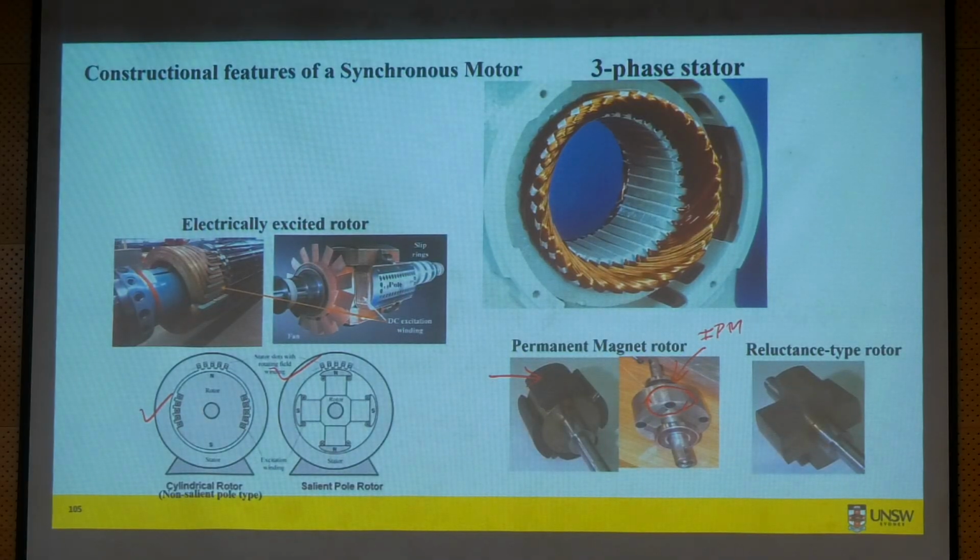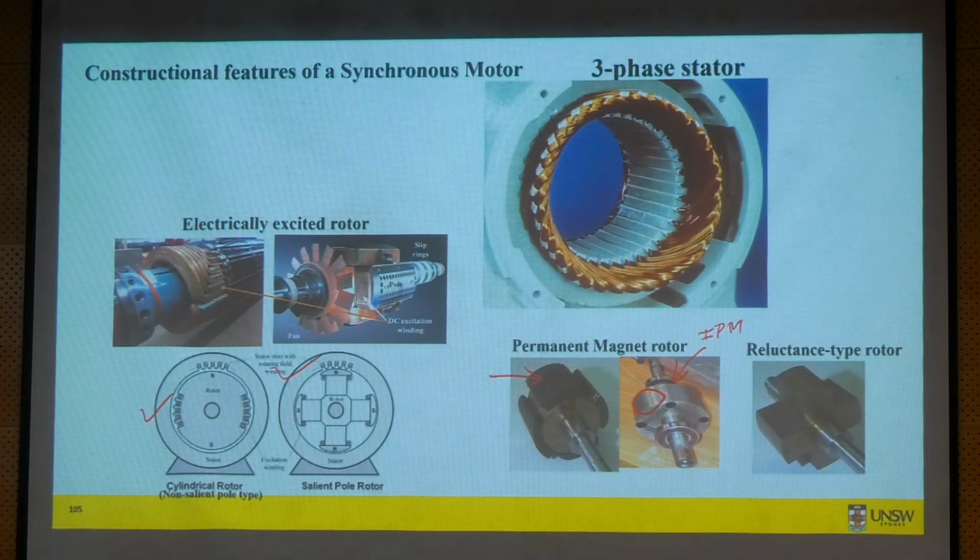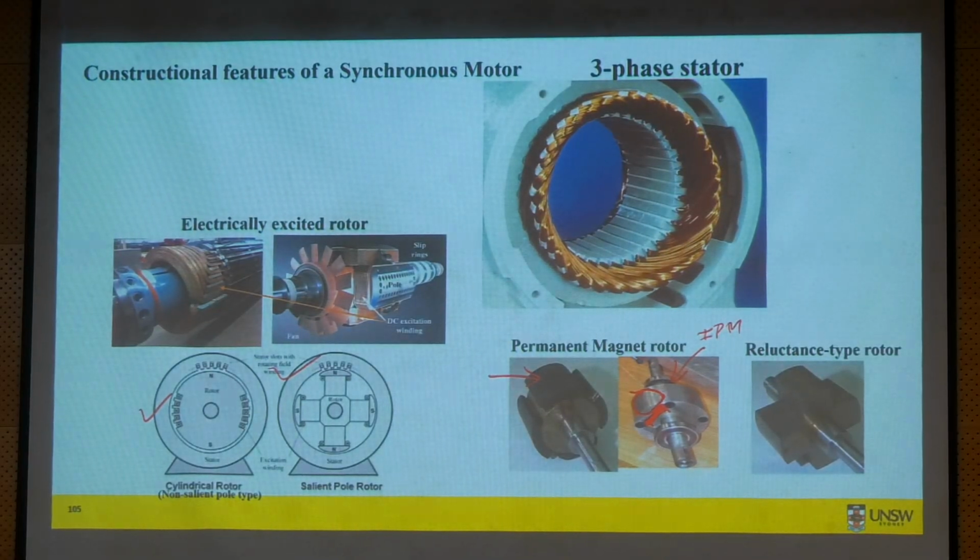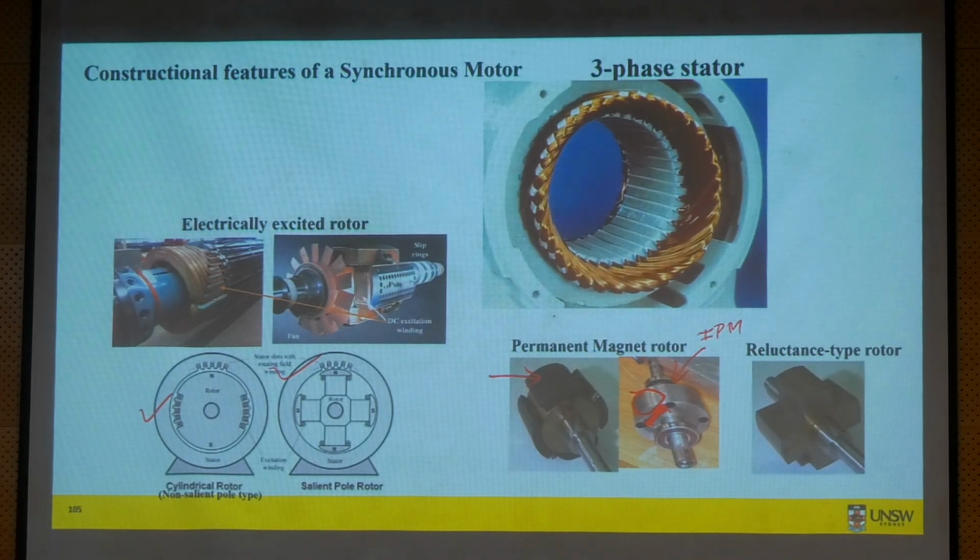Okay? If we do the Q-axis flux, the Q-axis flux will go like this. This is the magnet, this is the piece of magnet. So the Q-axis flux does not cross the magnet. It simply circulates over the top of the magnets. So it's only crossing the air gap, not crossing the magnet, so it sees a lower reluctance. And because of that, LQ is higher. So it's opposite. That's what we have to remember.